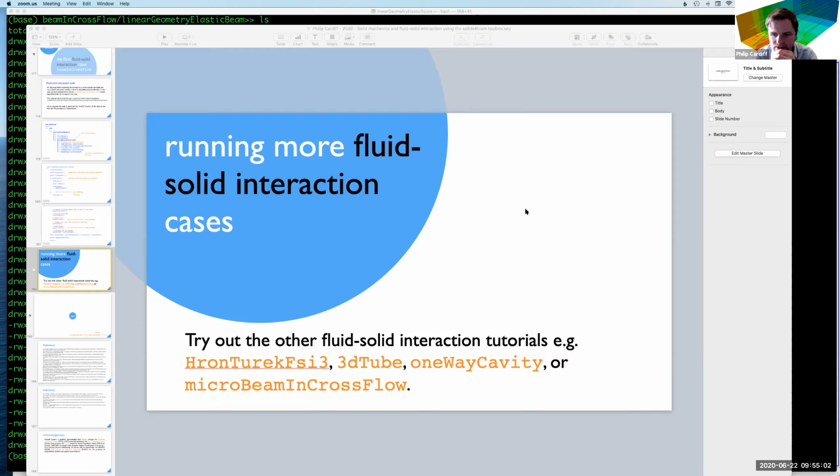Thomas: nonlinear elasticity, solids4Foam, evolution of displacement by implicit, explicit, which is derived from linear elastic. What do you think, can the solver be used accurately? So for numerical methods, we have accuracy, robustness, efficiency. Is it accurate? If you get your solver to converge, then solids4Foam is accurate. You can think of it like, if you're familiar with finite element, a linear finite element scheme. It's a little bit better because the stresses are second order, like the displacements, whereas in normal linear finite element schemes, the stresses are only first order. So it's a little bit better.